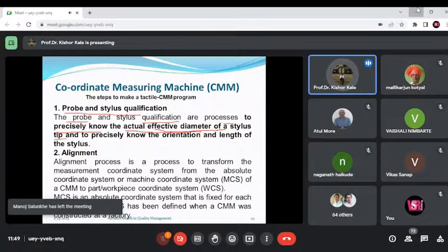They don't have the traceable dimensional geometry. So, as the correspondence is maintained in the data acquisition by CMM, it is possible to measure deviation of corresponding points on a manufactured feature or surface and the CAD model using CMM only and not using the scanners. So, that was what I was talking about.